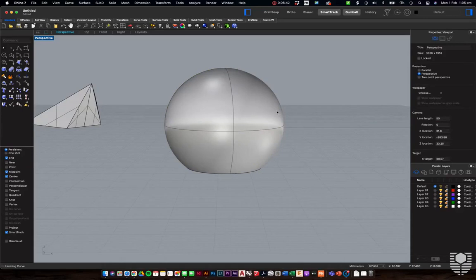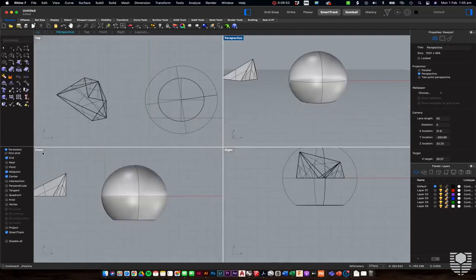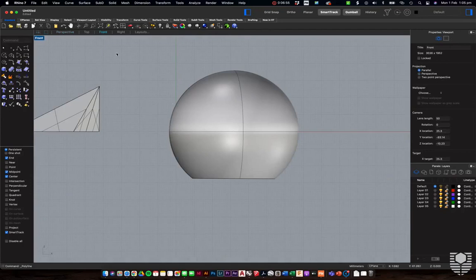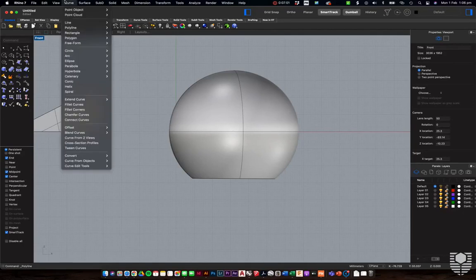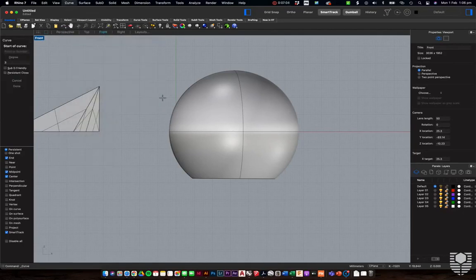All right, let's say we want to make a little bit more of a freeform or organic slice into our sphere that we have here. So much like we did with our surface command, we're going to think very carefully about what view frame we're in when we're doing our trim. So I've put it onto the front view now, and I'm going to make a freeform curve, control point curve, starting outside my sphere rather than on it. And I'm going to do some interesting shape like this. There we go, to finish.